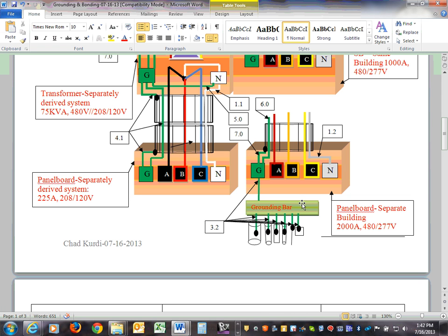The reason you're allowed multiple services is because the size is big. You're supposed to tie it to every existing ground electrode system. Here's the why. Imagine the north side that has the water there, and you take a feeder or branch circuit to that section. Now the water is sitting at one voltage level, and a fixture right next to the water line is sitting at a different voltage level. It could be a hazard. You could live for 150 years and nothing will happen, but it could be a hazard. So you have to bond them together.